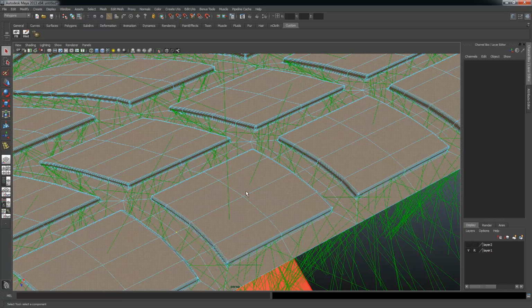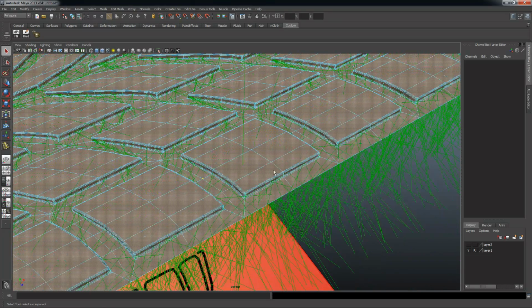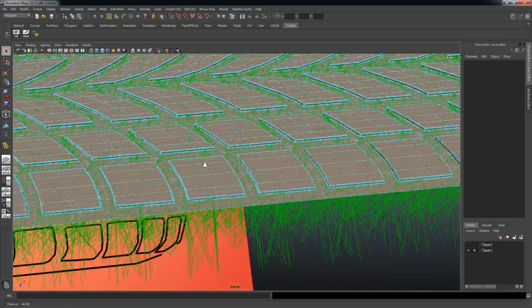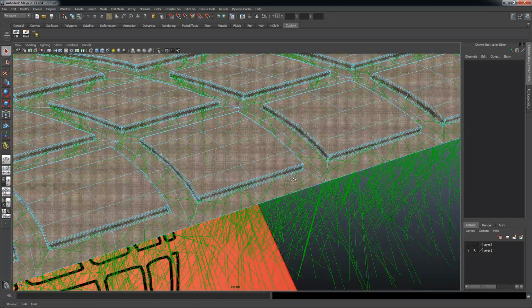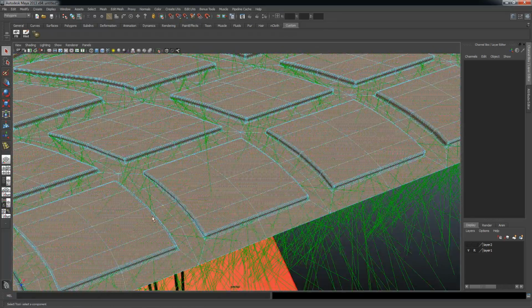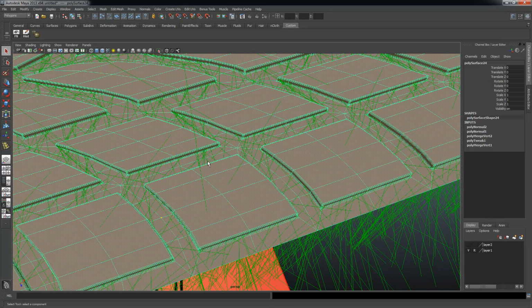It doesn't always work, and I have seen it where the face normals facing the wrong directions will also cause the Insert Edge Loop Tool to fail. But those are the two cases. Because I can't get it replicated here, I'm just going to keep moving on.